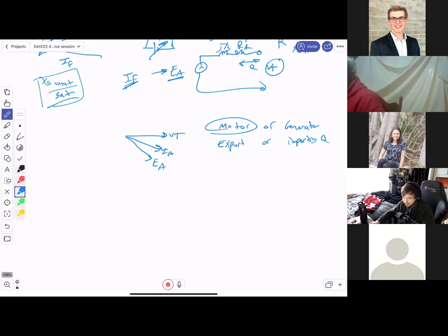So what makes a motor or a generator? A motor is only a device that imports power, real power. So what defines a motor is something that imports power. Something that exports real power is a generator. Importing or exporting reactive power doesn't even tell you if it's a motor or generator. That just tells you it's leading or lagging. That's all it does.